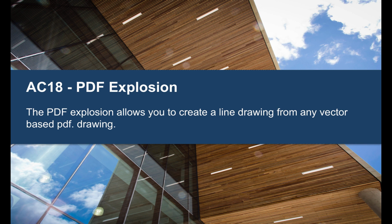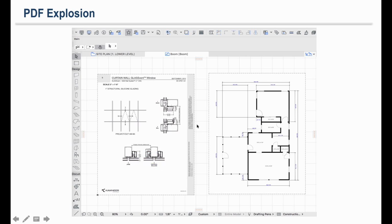The PDF explosion allows you to create a line drawing from any vector-based PDF and was included in ARCHICAD 18. One of my favorite features added to ARCHICAD 18 was called the PDF explosion. It allows you to take any vectorial PDF and turn it into a line drawing. You can place the PDFs in a worksheet. That's where I typically put them to use as reference using our trace and reference feature. But you can place any vectorial PDF into any of the 2D views within your ARCHICAD project.